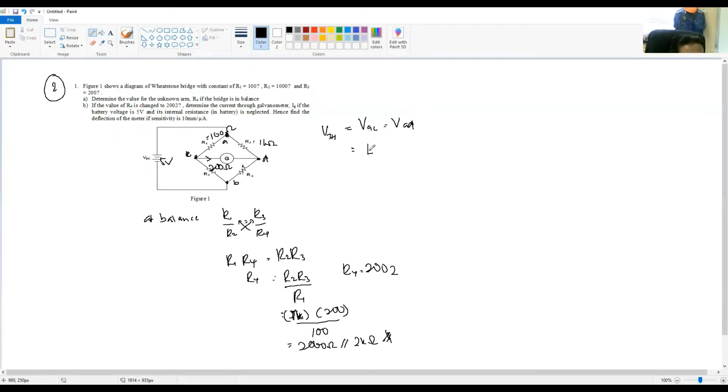The formula is already given, so you can check the notes on how the formula comes about. So R1 over R1 plus R3, minus R2 over R2 plus R4. First we have to find the VTH. Just substitute the values. E is 5 volts, and then R1 is 100.